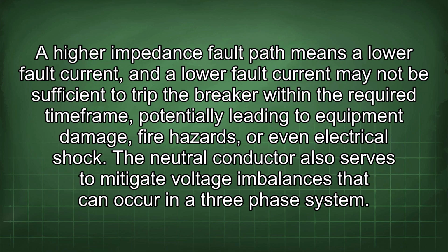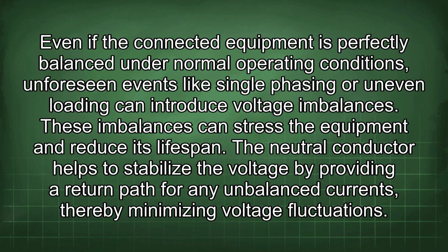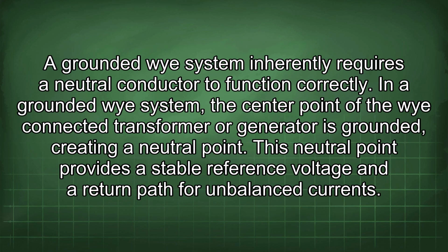The neutral conductor also serves to mitigate voltage imbalances that can occur in a three-phase system. Even if the connected equipment is perfectly balanced under normal operating conditions, unforeseen events like single-phasing or uneven loading can introduce voltage imbalances. These imbalances can stress the equipment and reduce its lifespan. The neutral conductor helps to stabilize the voltage by providing a return path for any unbalanced currents, thereby minimizing voltage fluctuations. A grounded Y system inherently requires a neutral conductor to function correctly.